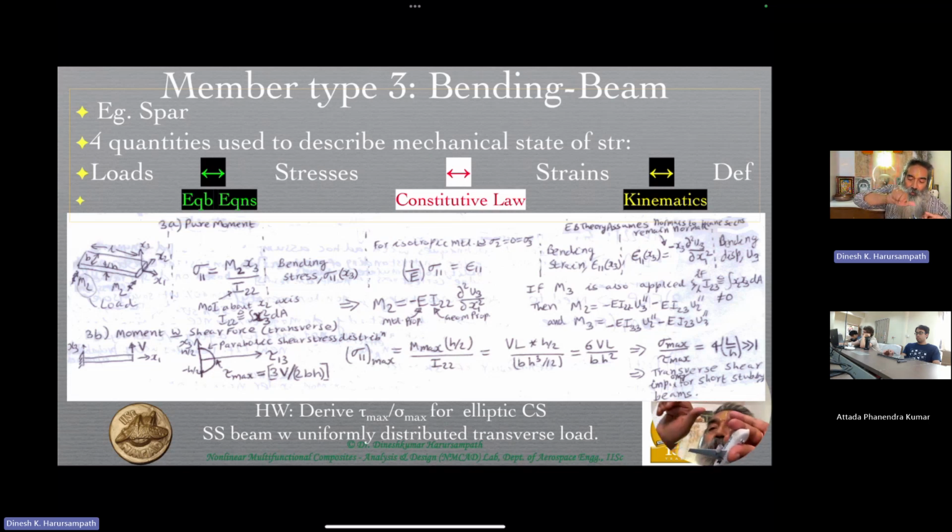The weights are causing a moment this way, whereas the lift is causing a moment this way. Similarly, the drag is causing a moment this way, whereas the thrust is causing a moment this way. So the thrust and the drag are causing opposite direction moments. The lift and the self-weight of the wing are causing opposite direction moments. So they just algebraically get added up. But they are along perpendicular directions. One is along the direction parallel to the velocity, the drag direction, and the other is perpendicular to the velocity, which is the lift, and that is going to take the other set of moments.